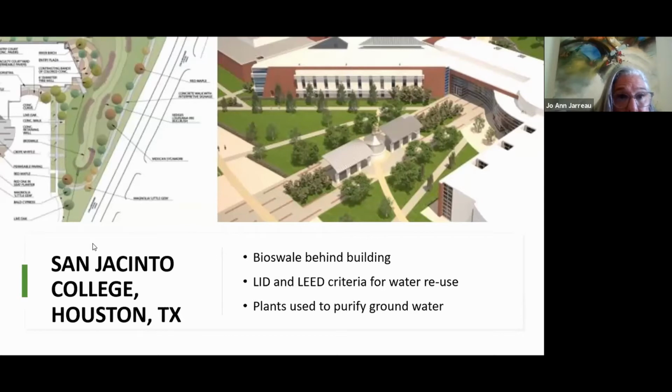I'm not looking at it to show you exactly, but as it goes down to the very bottom, there was actually a filtering pipe that had holes in it, with gravel and wrapped in filter fabric, that was connecting the two culverts together, on either side of that detention area.